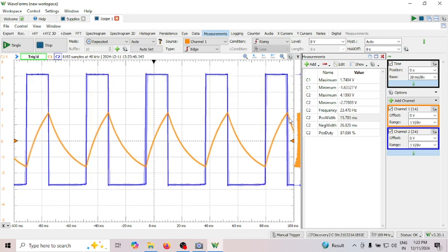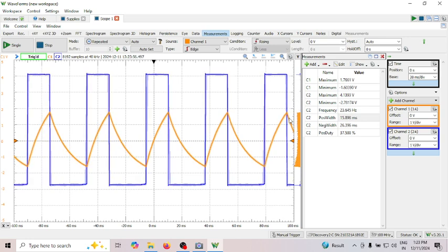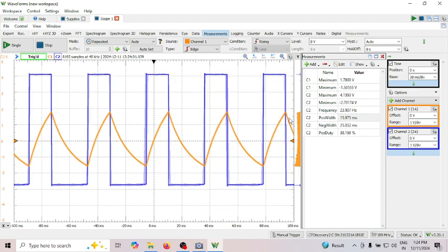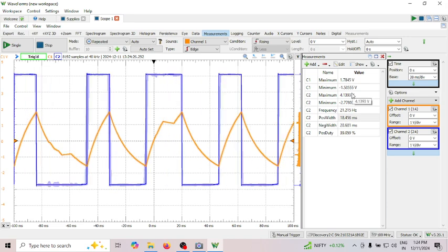But for getting high frequency square wave, it has got limitation because of its slew rate. So that's why you cannot get very high frequency signals. Even frequencies around 5 or 6 kilohertz is an issue with this 741. Suppose if you use a better op amp having good slew rate, you can certainly generate high frequency signals. So that's the limitation of this 741 IC, which is having a very poor slew rate. Slew rate of this IC is 500 millivolt per microsecond. That is a limitation. That's why I cannot get very high frequency.